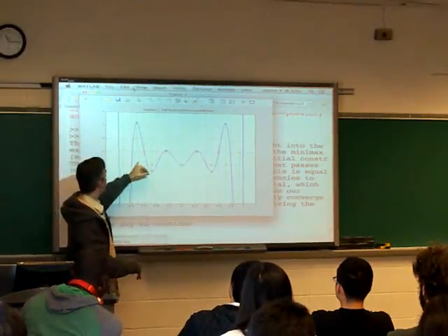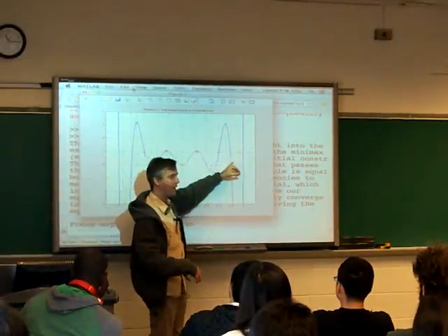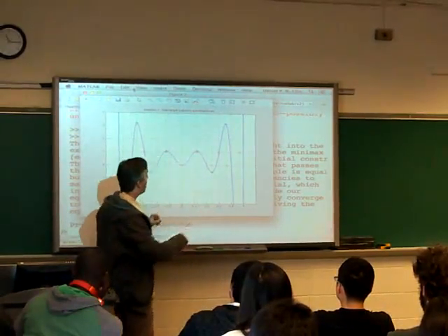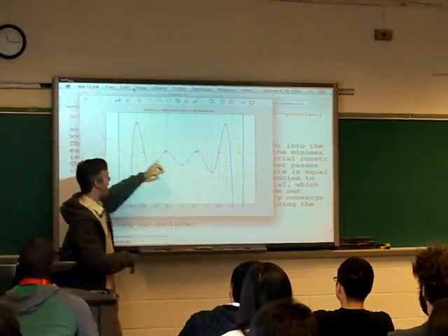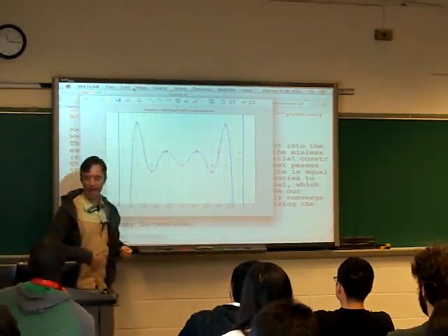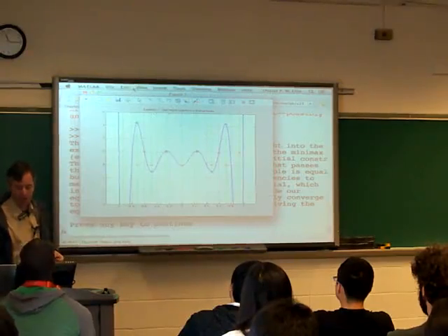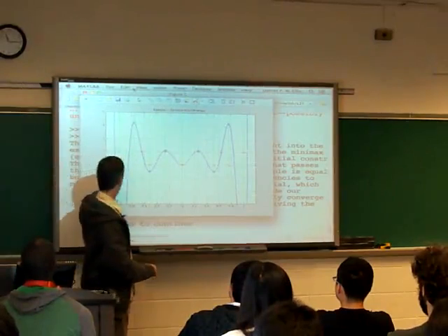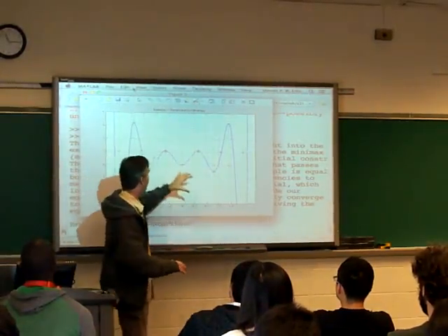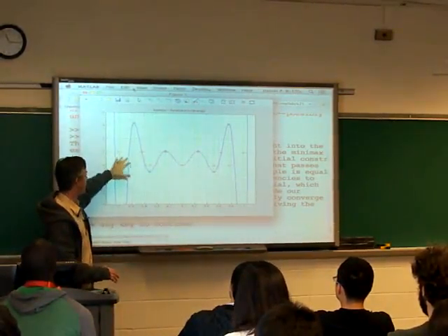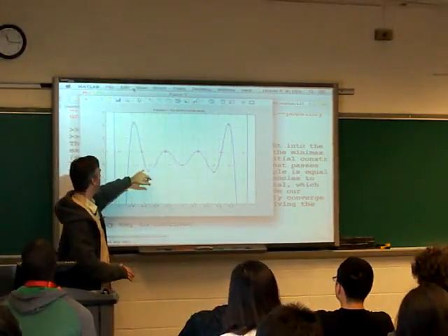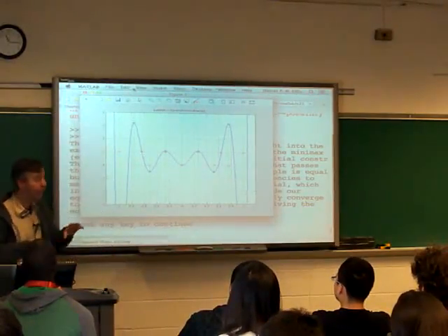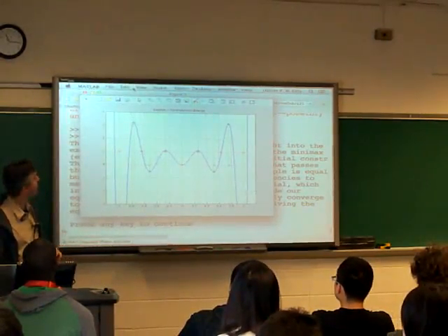Now, we don't care where these frequencies in the middle occur. We just care what values they have, so we're able to move the omegas around. But we do care where the ones at the edge occur, because those are our band edges. So then we stretch the whole x-axis to make these things line up to be the points that we want. But now we've got a new set of constraints, a set of these 11 frequencies. We know what we want the values to be there, but now the frequencies are slightly non-uniformly spaced, and we can fit the polynomial to those instead.